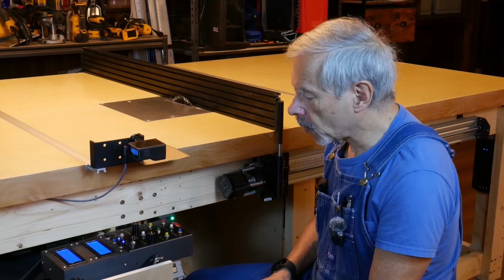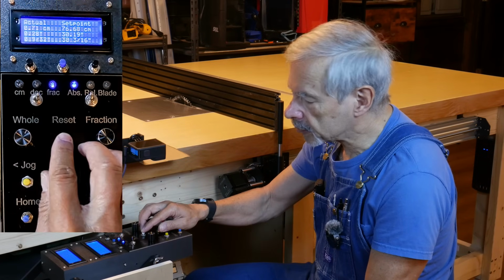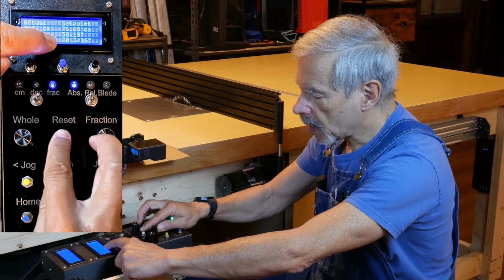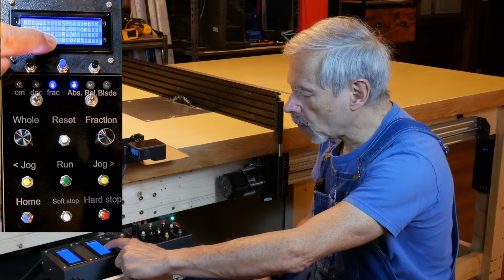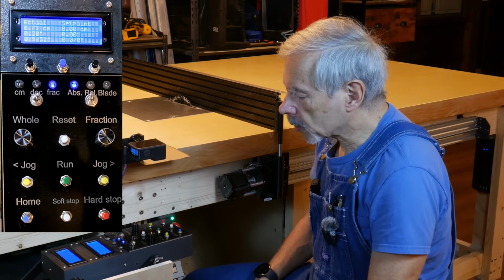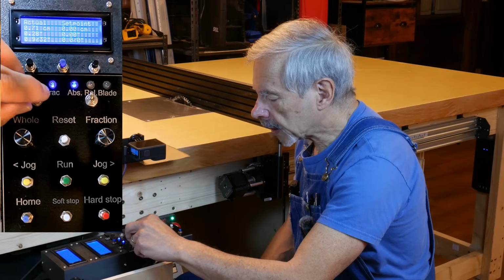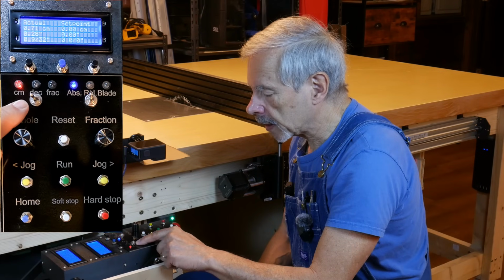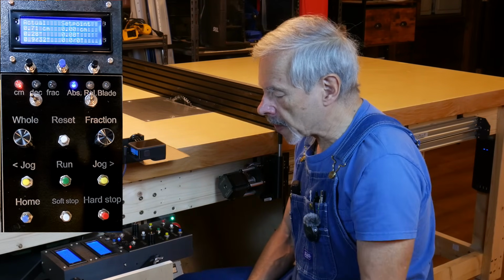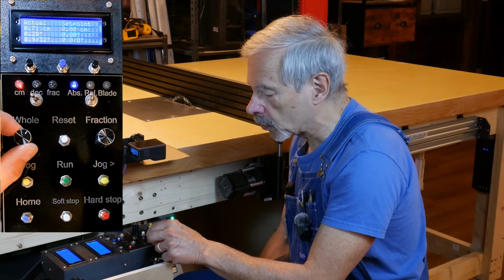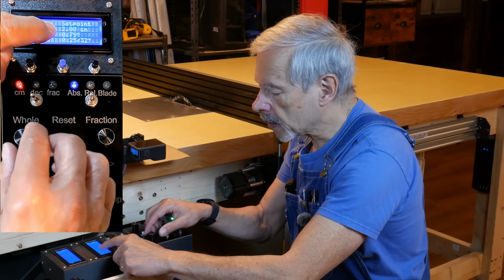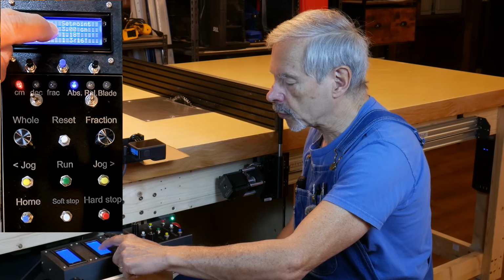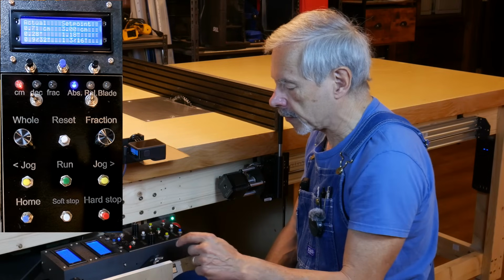I'll actually show you, and for that I'll reset the set point from the last set point that it was at. I'm resetting it to 0, and now I'll set a new set point. I'll actually work in centimeters for that because I can measure that more accurately. I'm setting the input system to centimeters, and I will tell the fence to move to a position of, here now the centimeters are of interest. I'll tell the fence to move to a position 3 centimeters away from the blade.